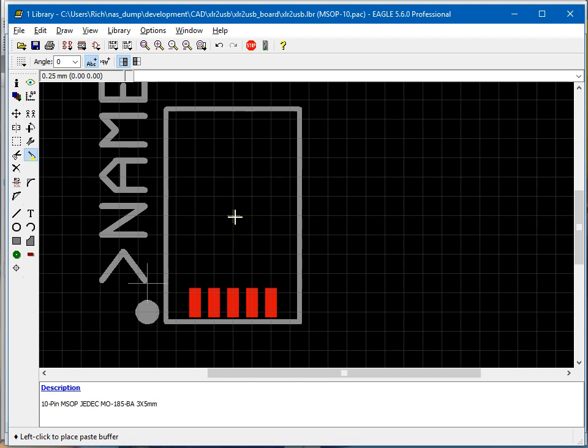Now you notice right now I'm on top of them. I can slide a little left, but here's the magic. I'm right-clicking, and right-clicking rotates the group. I'm staying at the origin, which means that it's now rotationally symmetric about the origin. This is really handy for quad flat pack packages that have 4 corners, and you don't want to keep flipping them around or something like that. This is a handy trick. It's not so useful on this one, but it is a good, simple example. We probably didn't save very much time. Click once, and there we go.